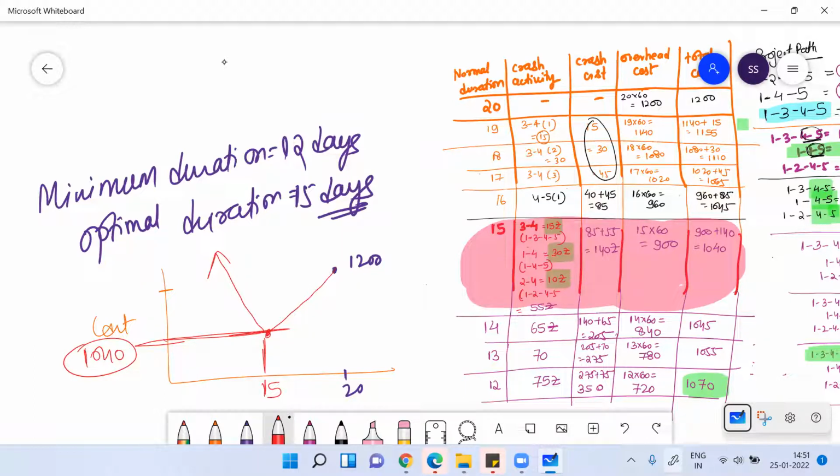If we do not pay much attention to the time parameter, automatically the cost will keep on increasing, because there are some forms of cost which are direct costs, which do not change, but there are other forms called indirect cost. This indirect cost will keep on increasing as the time of the process increases. So we can introduce the concept of crashing cost. By using crashing cost, ultimately we can reduce the duration of completing the work.